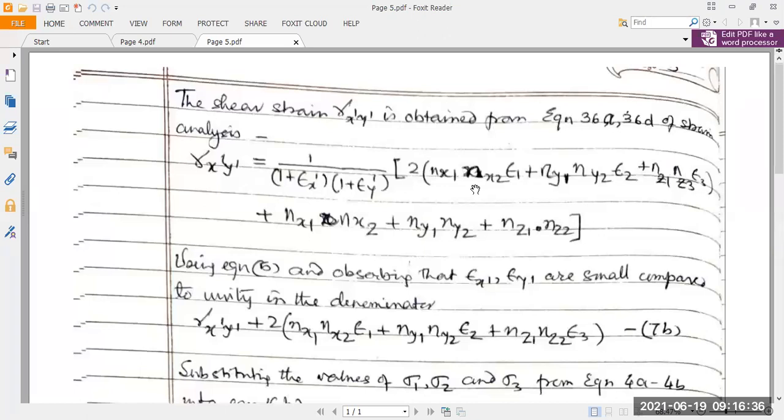Sometimes it happens that due to the action of external force, PQ and PR with internal angle theta are distorted and moved to a different position, like P dash Q dash and P dash R dash, with the angle in between changed to theta dash itself. And we know that our shear strain is given by the angle, tan theta, or as it is extremely small, equal to theta dash, which is given by this formula: gamma x dash y dash, equal to tan theta or theta.